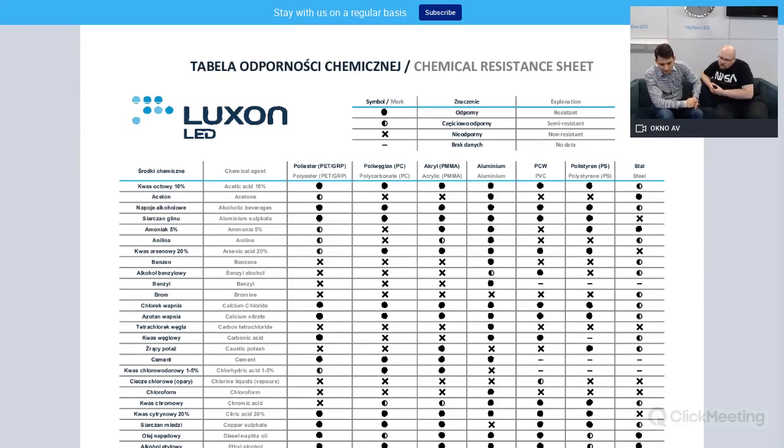We have another question from John, more specific also: the sealing between the upper and lower part of the fixtures. What type of rubber do we use? Pure EPDM. Depending on the product that we use, this type of application uses a poured polyurethane. This is hot poured polyurethane inside the housing. So it's not EP and it is not EPDM.